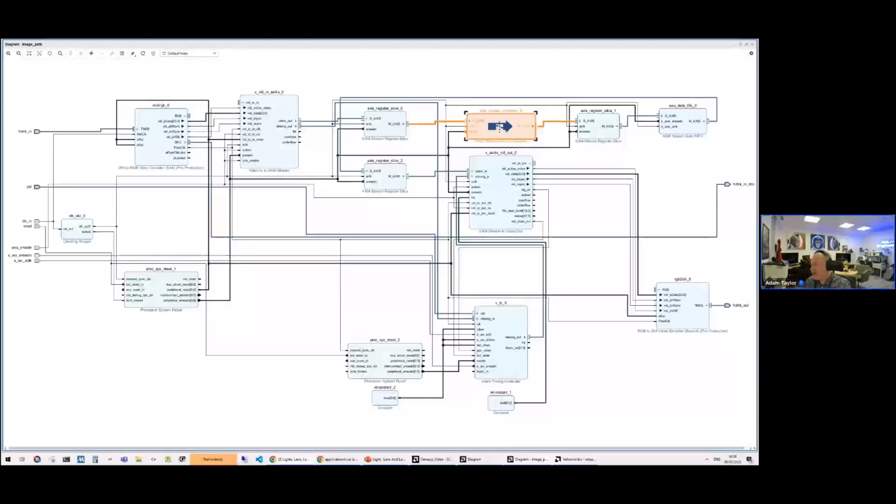Andrew, actually all of the IP cores in this example are free. There's not a paid IP core in any of these examples. They all come free with the base version of Vivado, and the MIPI CSI-2 core is also free with the base version of Vivado. If you've got an FPGA that has the H.264 codec in it, you can get all that up and running free.